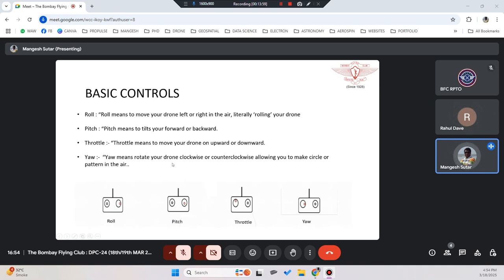Normally using yaw and pitch motion, we always control or make the patterns. We can make a circle or we can make a square, all those things we can do. Basically yaw is the option when you use the left stick, because with yaw you are changing the direction. When you mix yaw with pitch, you are turning as well as pushing forward, or going back.